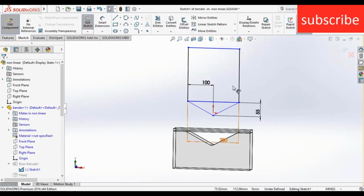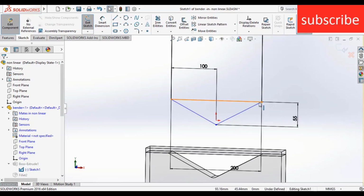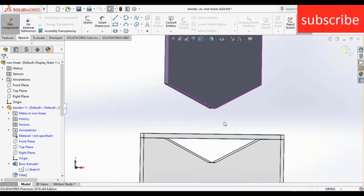Here, you can see the dimensions so you can make it yourself. Remember, the main thing here is the triangle only. The triangle total length is 200 mm, the distance from the center is 100 mm, and the depth of the triangle is 55 mm. Make sure this point is at the center of this line. It doesn't matter what the height of this is, you can make it as per your requirement. All you need to make sure is that the length of this remains the same and there is a fillet of 10 mm at the end here. As you can see, it's curved, so I just used a fillet command here.